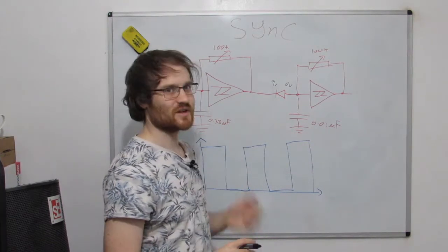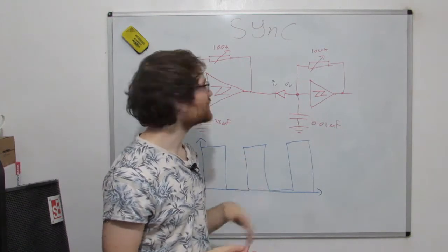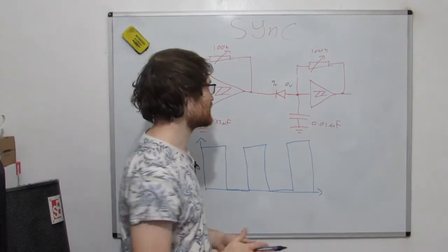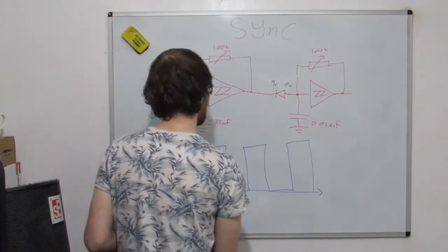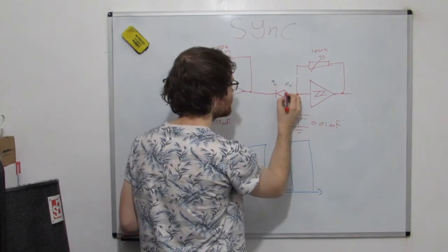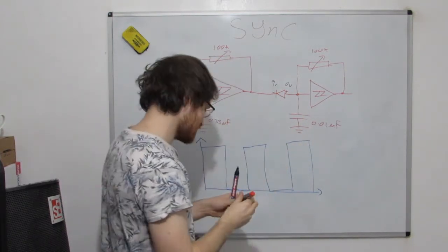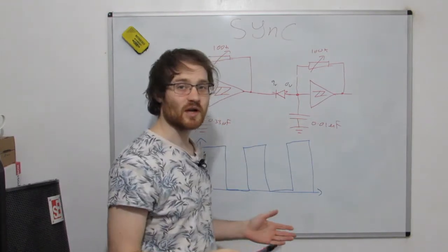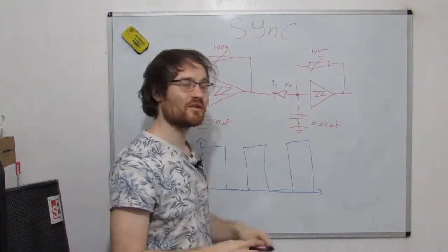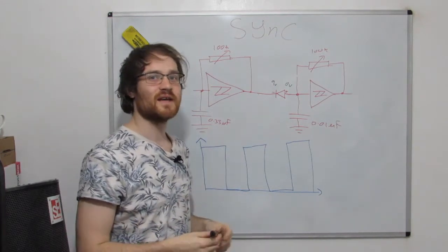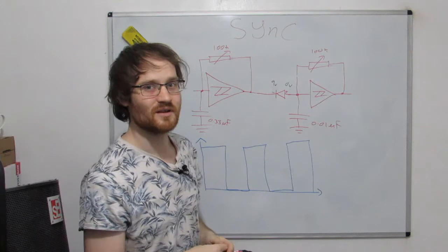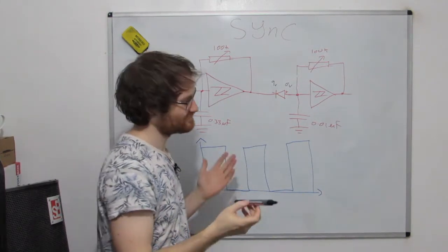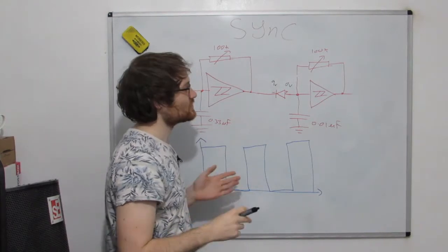There will just be a voltage drop across that resistor proportional to the amount of current, which at the moment is 0, because let me mark the anode and the cathode on here. This is the anode and this is the cathode. So you can see the cathode is more positive than the anode, so no current is going to flow. There is a tiny leakage current, usually in the order of 10 to the minus 14 amps, which is 13 noughts and a 1 amp. Let's forget about that.